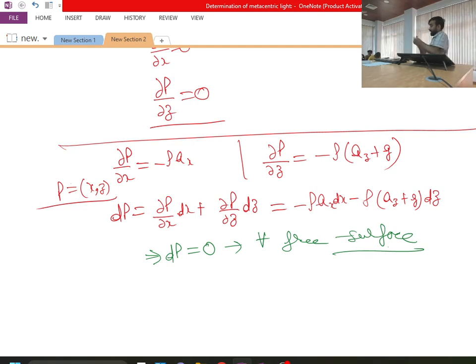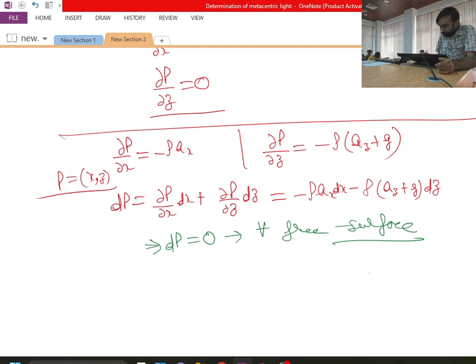Yes, at free surface it will be experiencing because it is tilted like this. So I understood your doubt is that one end should have high pressure. Let me tell you. Free surface is now like this. If you measure pressure at this point, then what will be pressure? This is P naught, say this height is H1. What will be pressure here? P naught plus rho G H1.